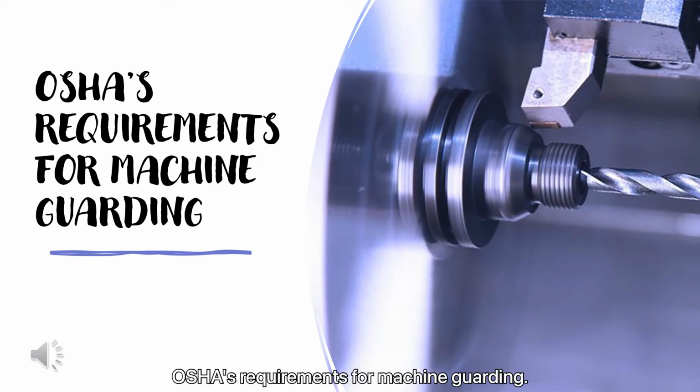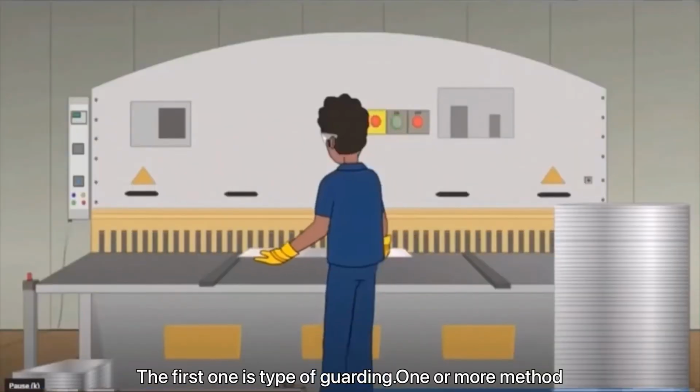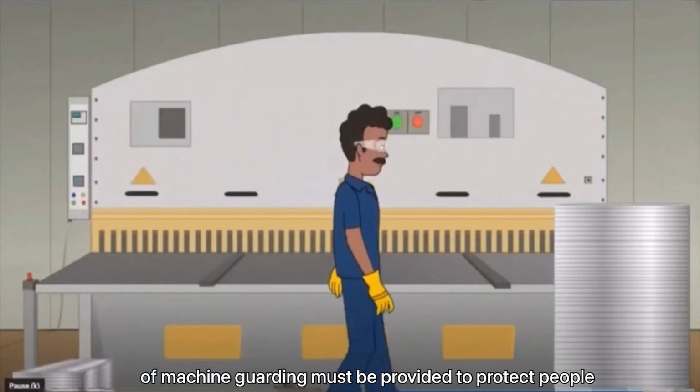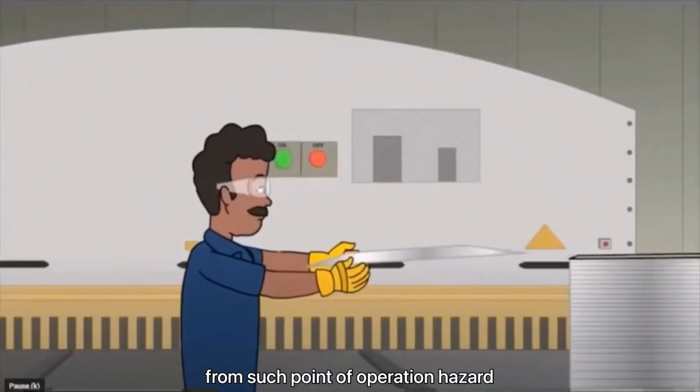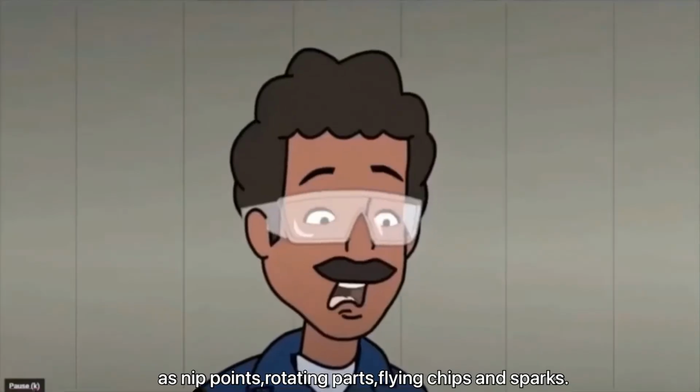OSHA's requirements for machine guarding. The first one is types of guarding. One or more methods of machine guarding must be provided to protect people from such point of operation hazards as snap points, rotating parts, flying chips, and sparks.